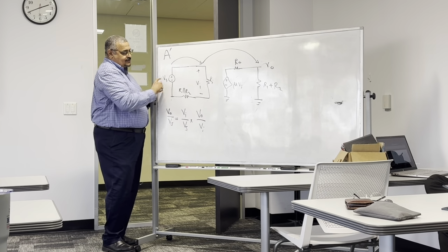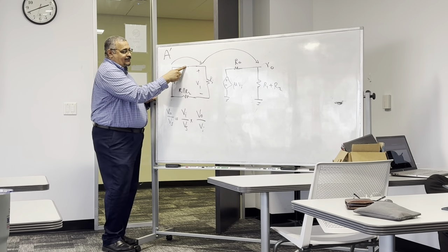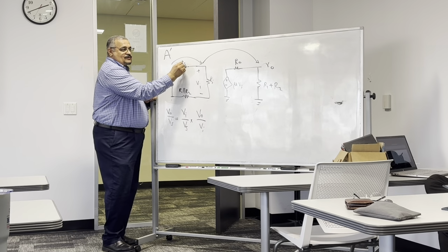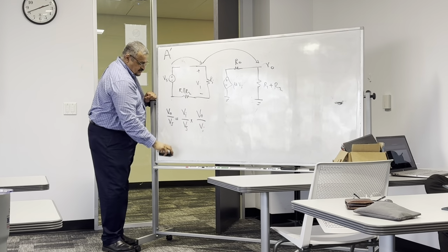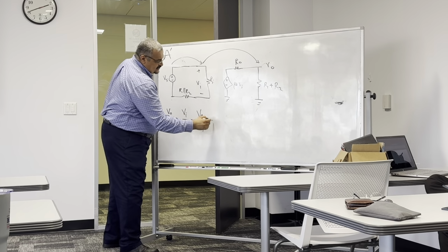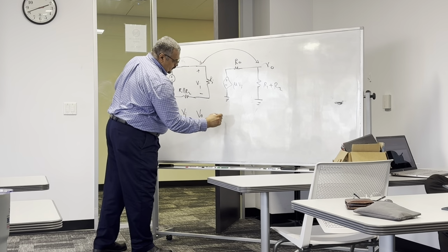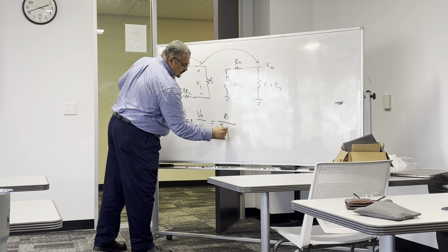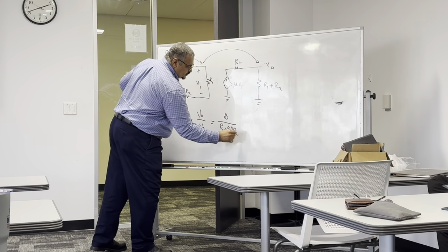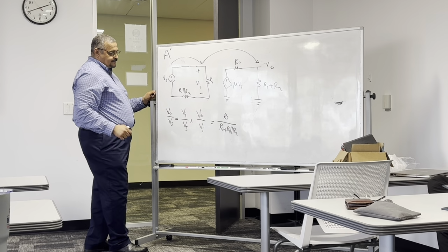This is a voltage divider, right? And if you have Rs here, you have to consider Rs in the voltage division, okay? But now, since we don't have it, we're going to keep it this way. So this is Ri divided by Ri plus R1 parallel to R2. Okay? So this is this one.